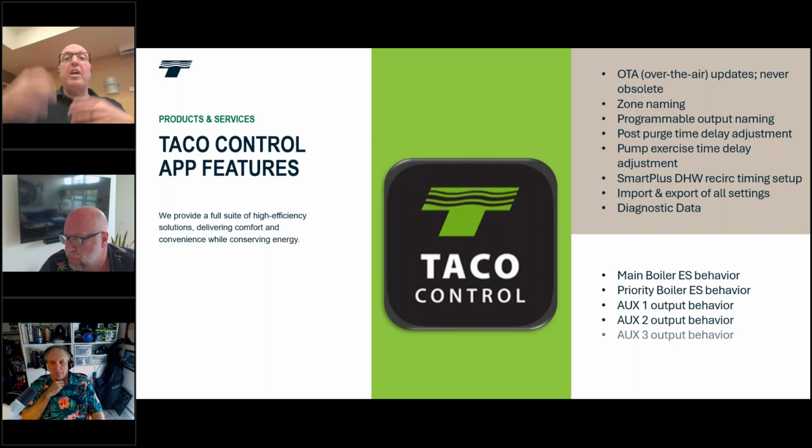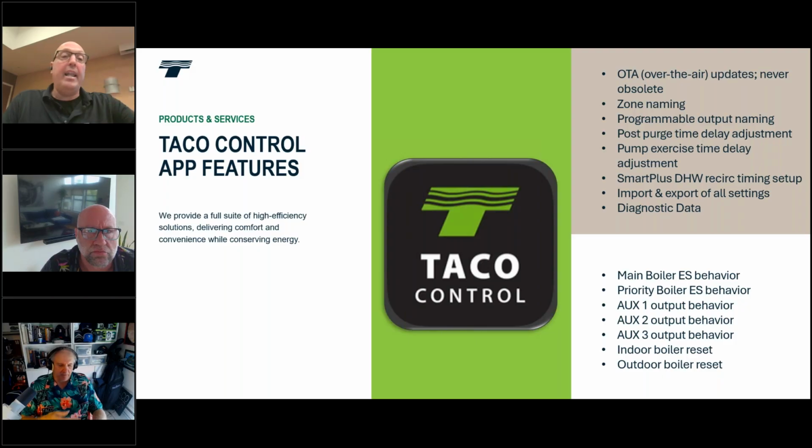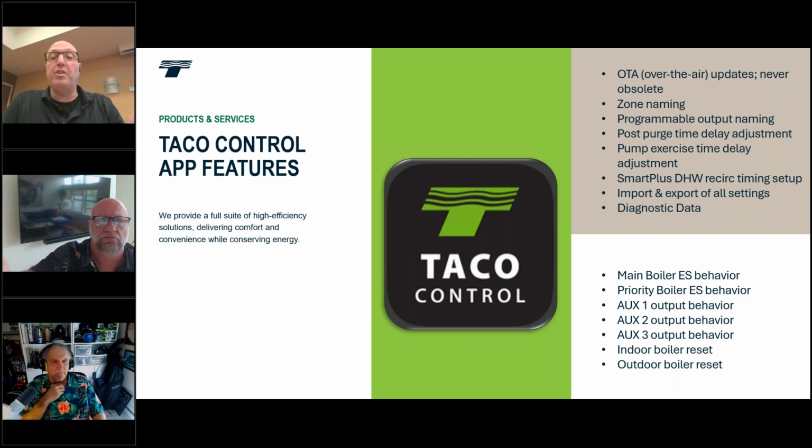What can we change? Well, we can change the end switch of the boiler, we can change the priority end switch. We can change the auxiliaries, what tells them to turn on, rather than using the default settings. And like I said before, also through the app, we're going to change settings in the indoor reset or the outdoor reset, one or the other. You're not doing both in the same system. You pick one versus the other.